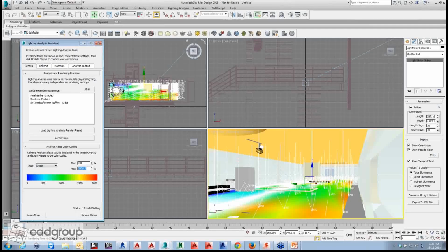So this gives me an idea that there is supposed to be more opening, or more openings have to be added in that area to get the desired amount of light. Reasonably, you always look at the charts for how much lux you require for a particular environment. For example, a living room would need 300 to 450 lux, or for a warehouse you need at least 250 lux in that area.